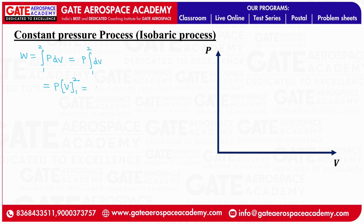So we can write pressure times upper limit minus lower limit, V2 minus V1, right? This will be the work done expression. Work done is equal to P(V2 minus V1). This will be the work done for constant pressure process, right?